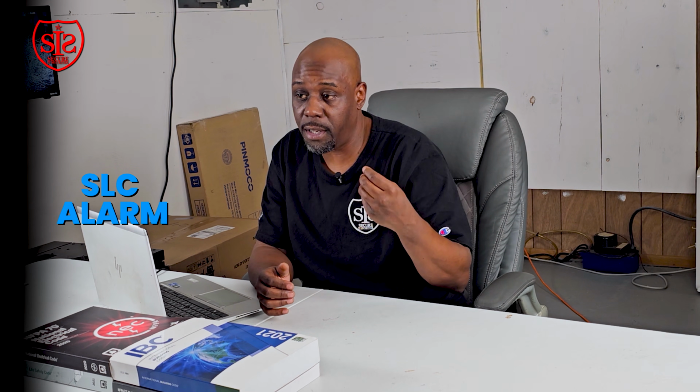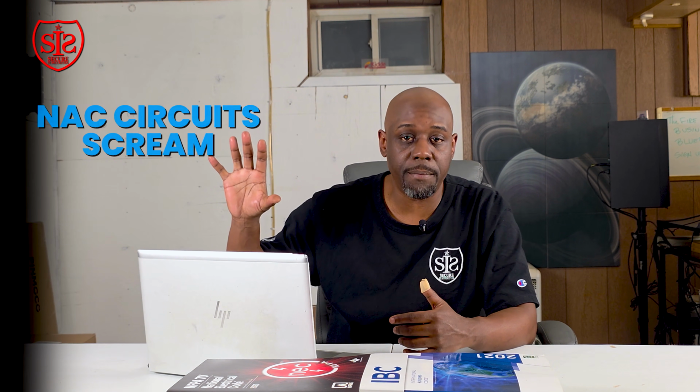So there are 2 very distinct differences between the 2 circuits that you're working on, and you cannot confuse the 2, because one landing on the other can disrupt that whole entire circuit and your whole entire fire alarm system. So you don't want to do that. So when an SLC receives an input event like an alarm, the system now interprets that, and the NAC circuit just screams. They scream the horn strobes, they scream the chimes, they scream the bells, or they will actually output some voice annunciation on a speaker if you have speaker strobes on a voice system installed on a fire alarm